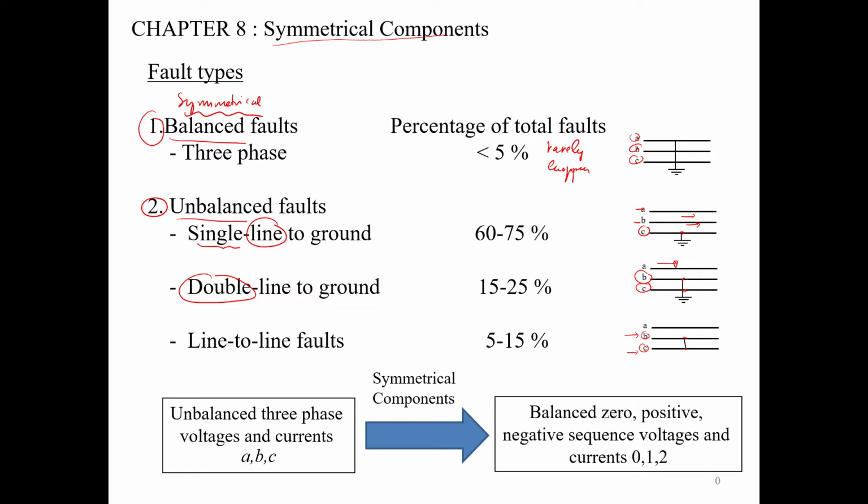So why are we interested in learning the symmetrical component? Because the symmetrical component will be the tool to analyze unbalanced voltages and currents. We have learned from several courses in basic power systems that the main assumption we have made in learning three-phase power systems is that the three phases are balanced.